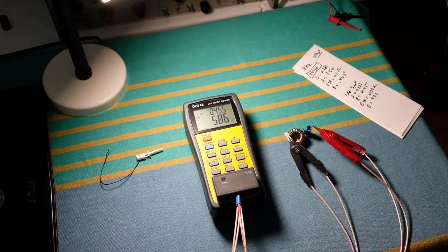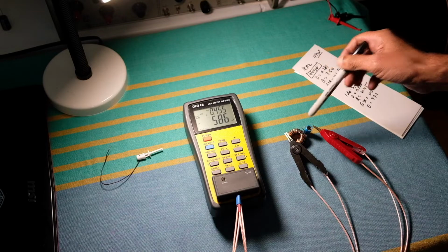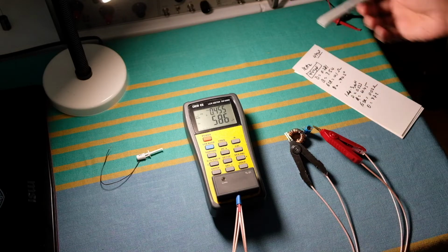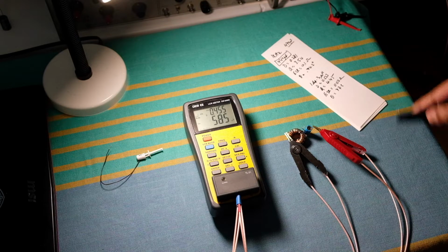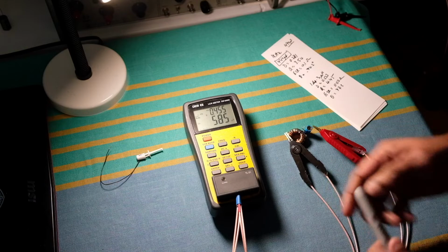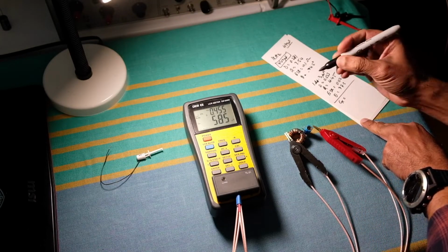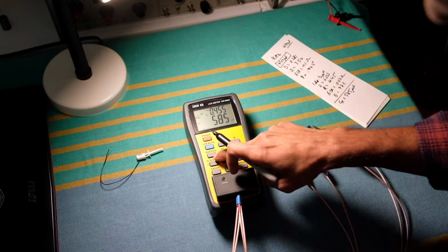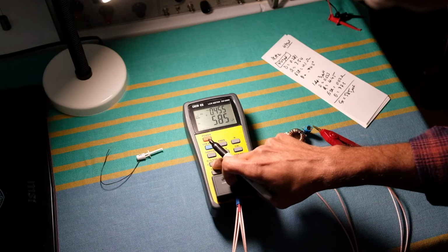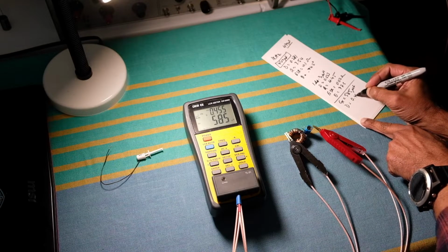Okay, so now I've connected the two in series. So this inductor acts like a very long lead as far as this capacitor is concerned. I'm just trying to enhance the effect of inductance to prove my point. You can see now that the value of the capacitance read is 585 microfarad. So Cx, or the C effective now, is 585, and the dissipation factor, as I said, increased to 0.455.